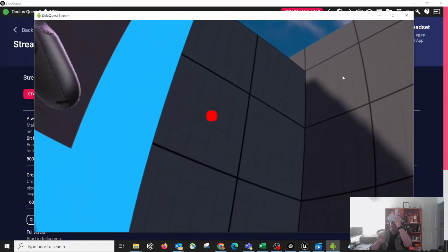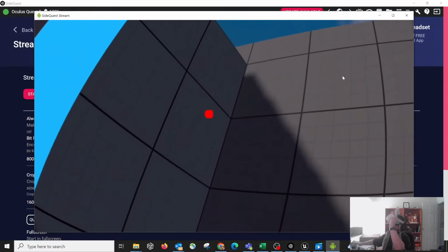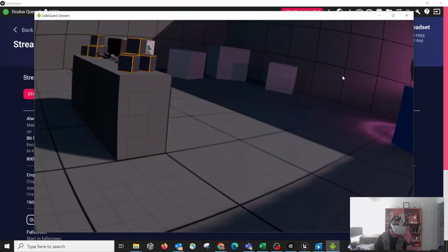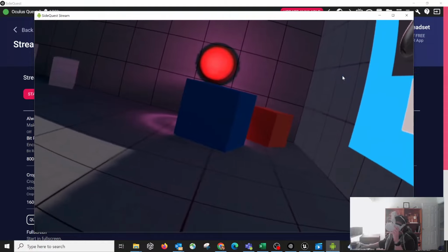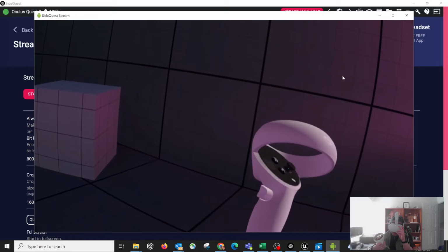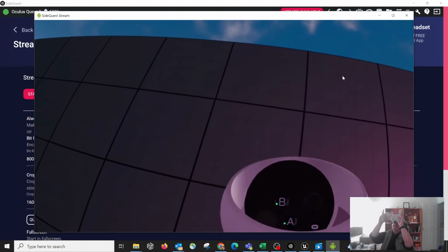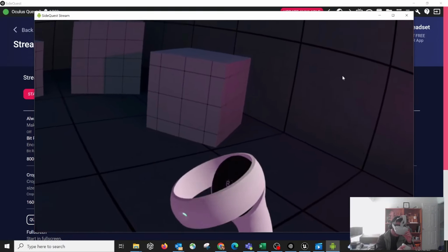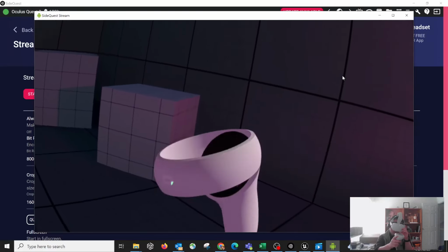The way I did it is I make this wall a movable object so you can cast dynamic shadows. Dynamic shadow means the shadow can interact with the dynamic objects. Right. So here I can see, but if I navigate to another side of the space, here you see this controller does not have any shadows. The reason is this wall is not a movable wall. It's a static wall. So the shadow you cast here is actually a static shadow. The static shadow does not interact with dynamic objects. So this is kind of different.